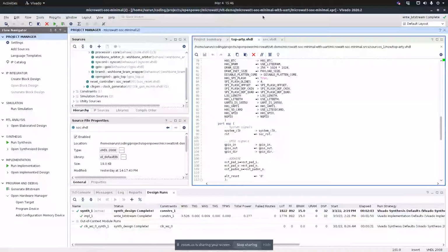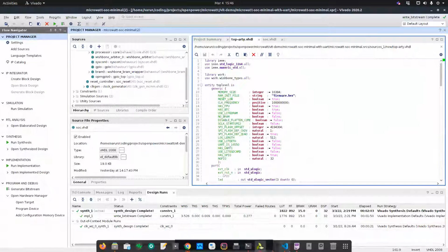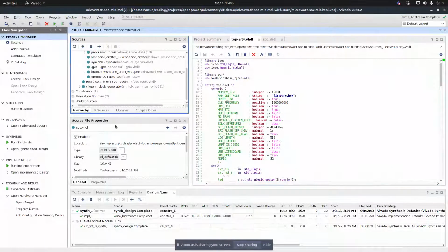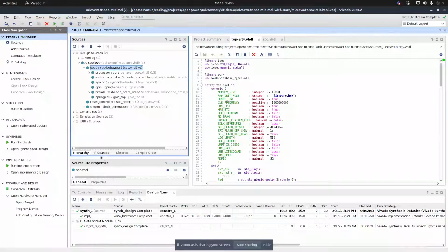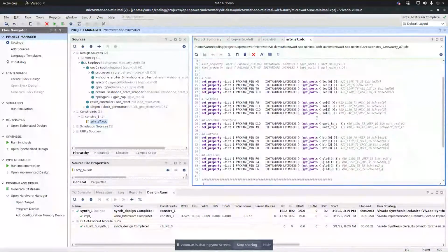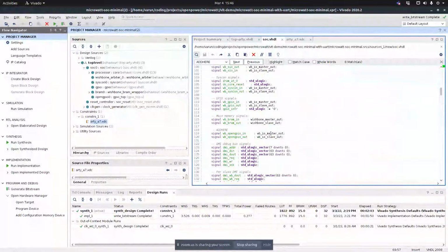You can clone that repo and start experimenting. You can easily port it to other FPGAs as well. For Xilinx, you might have to work with the XDC constraint file here. If you are on a different board, how the LEDs and buttons are wired might be different. And the other things should be fairly easy.